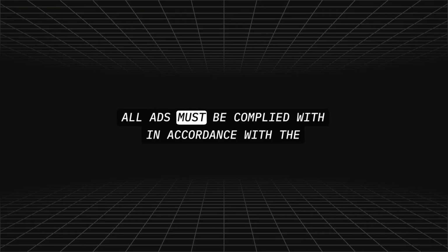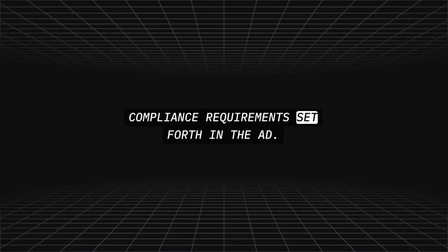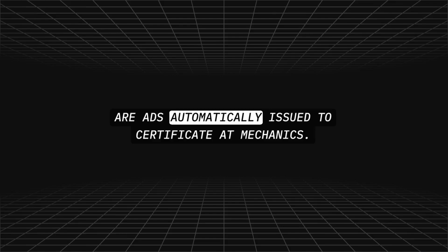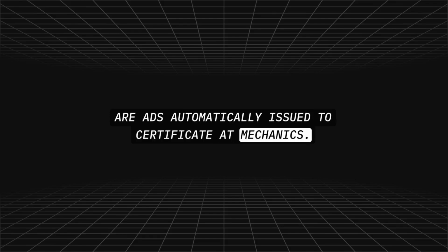When must airworthiness directives be complied with? All ADs must be complied with in accordance with the compliance requirements set forth in the AD. When is the summary of ADs published? Every other year. Are ADs automatically issued to certificated mechanics? No, they are issued to owners.